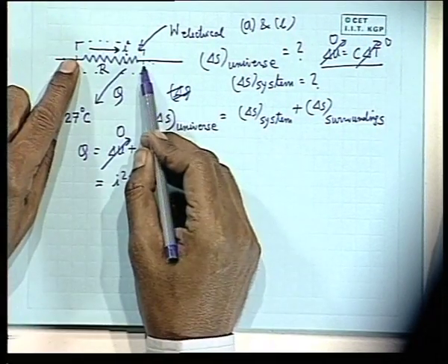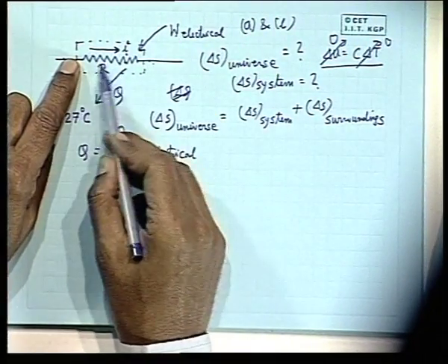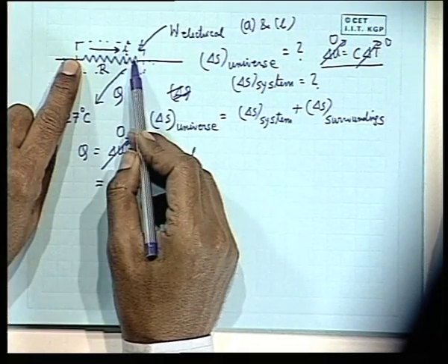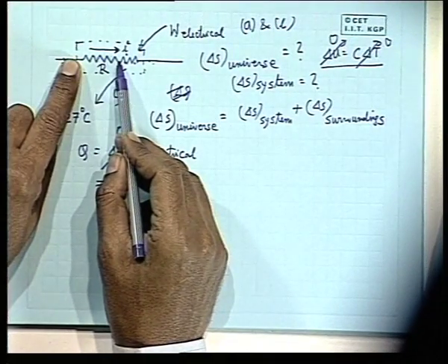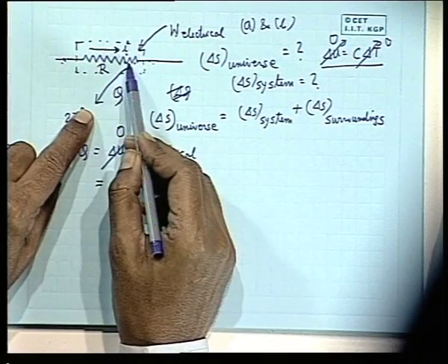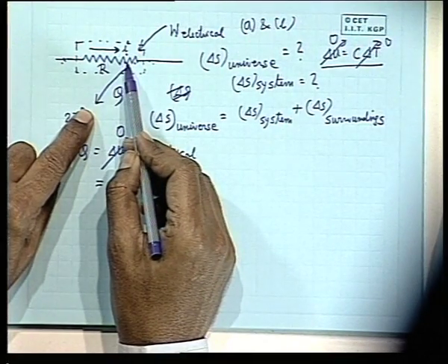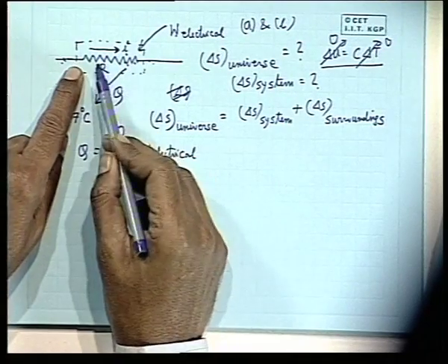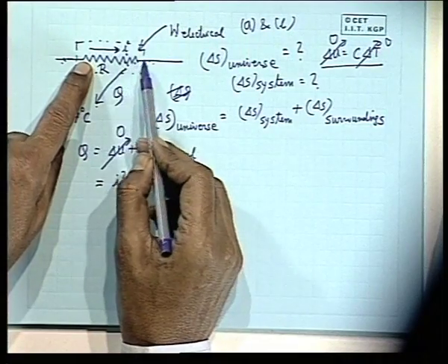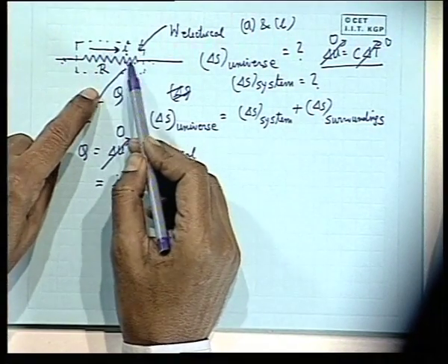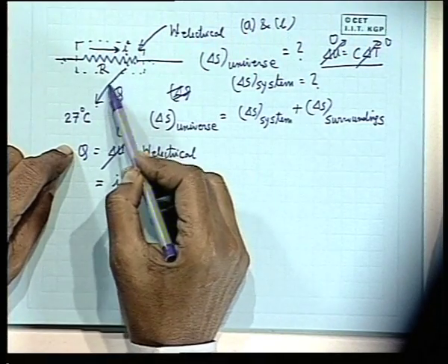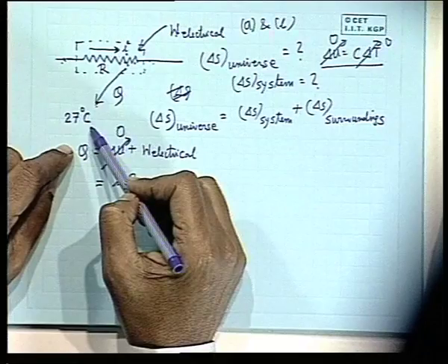Physically, this electrical work is transferred to the system, and because of electrical irreversibility, it is first converted into internal energy. Then immediately the heat comes out because of the increase in internal energy, so that the internal energy is restored to its initial value. So, in the system the electrical work is ultimately coming out in the form of heat to the surroundings.